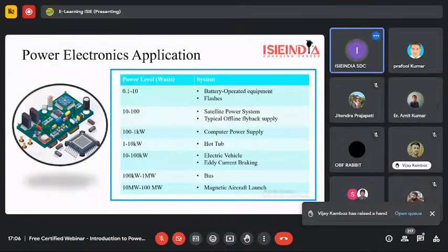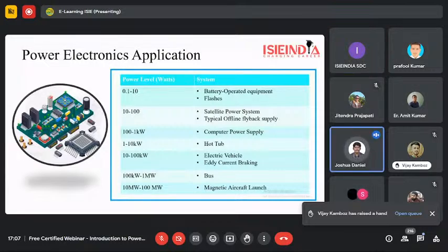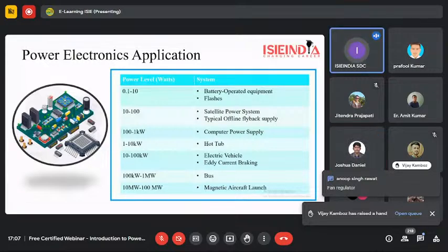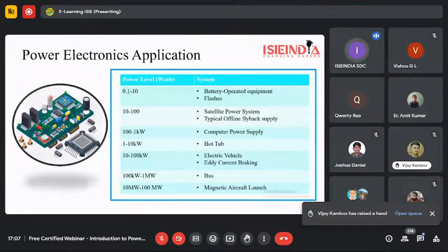So someone said chopper. Can anyone tell me where we use a chopper? Basically, choppers use a MOSFET, and convert input DC into a variable DC supply. One thing is that the inverter, rectifier and chopper are all combinations of switches. These switches perform switching at a particular instant according to the circuit configuration, and because of that switching, we get the required output.